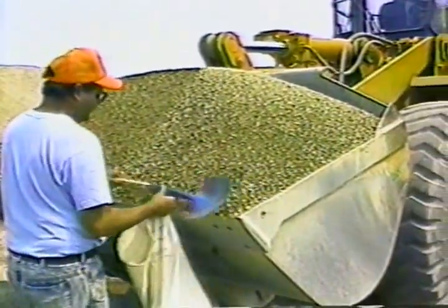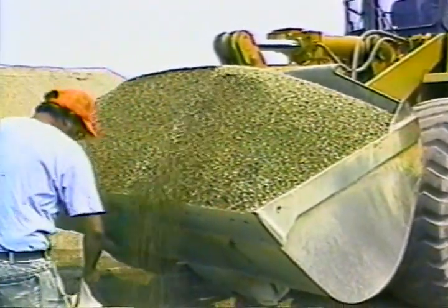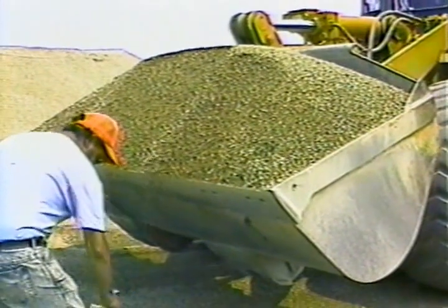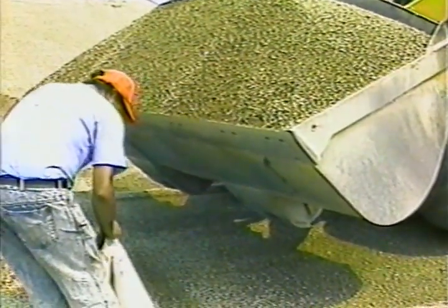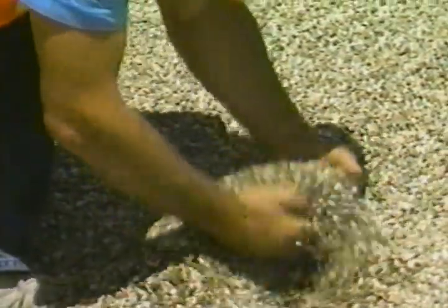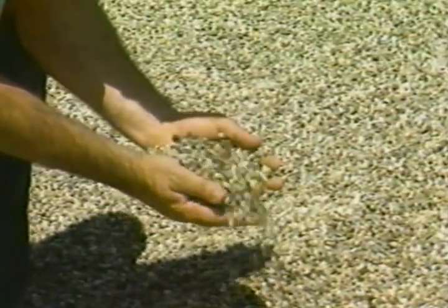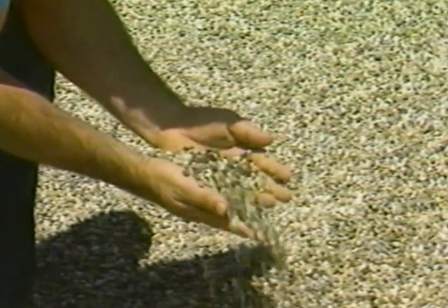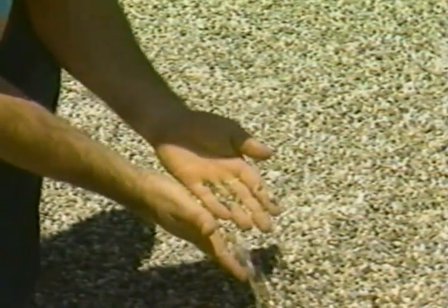Be sure the chips to be used meet your agency's specs. The size and type of aggregate depends on the number of applications to be made and the type of binder to be used. The aggregate may be gravel, crushed stone, or slag. Individual particles should be cube-shaped and as nearly of one size as possible. Graded aggregate should not be used because the smaller material would immerse completely in the binder.